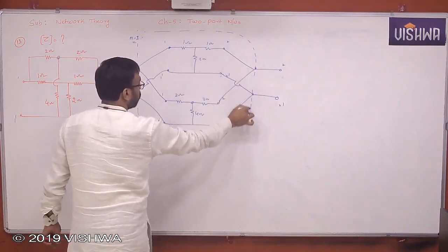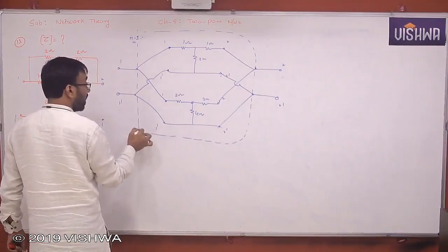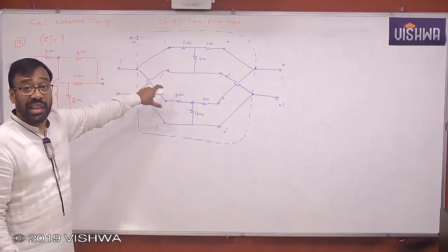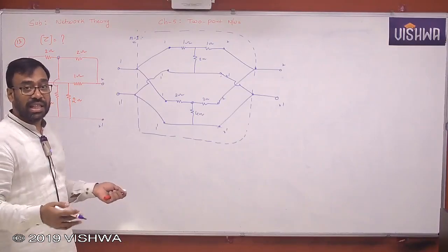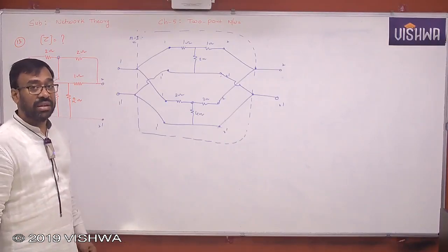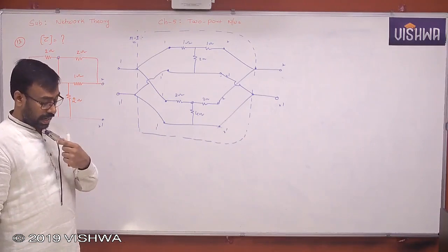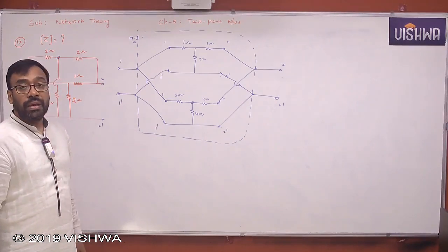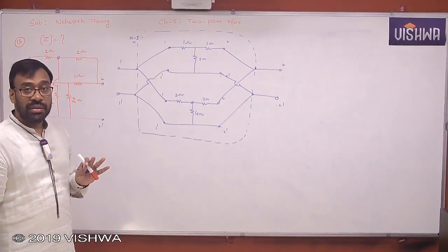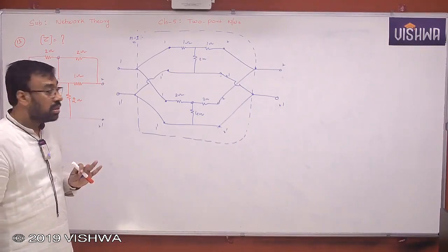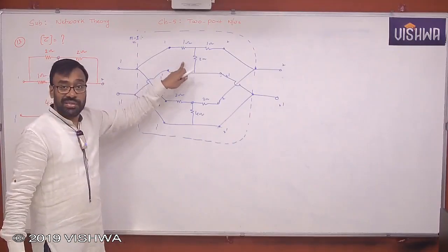Now these two-port networks are connected in parallel. If I can replace these two by a single one using our methodology, Y is nothing but sum of individual Y matrices. Remember, when two-port networks are connected in parallel, which parameters are more suitable to deal with? Y parameters, right? But T models are given.